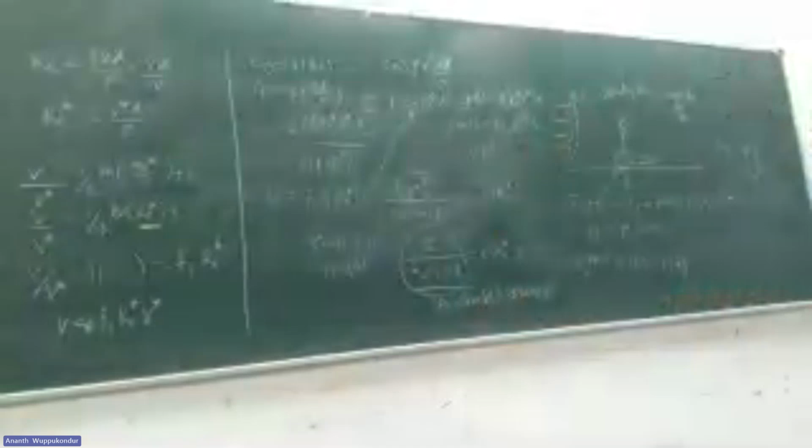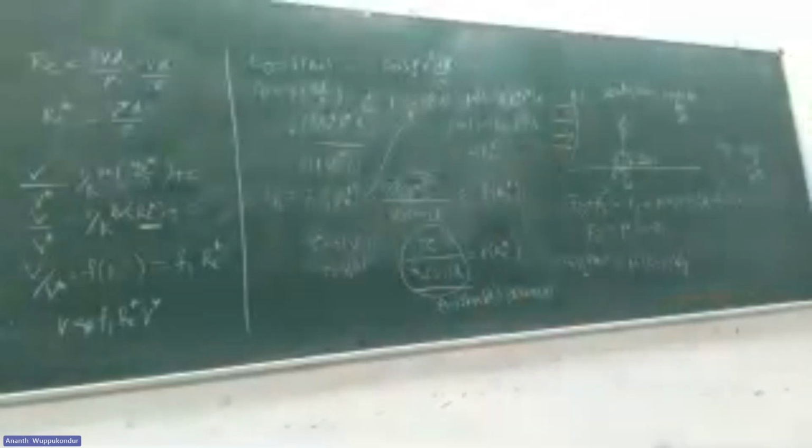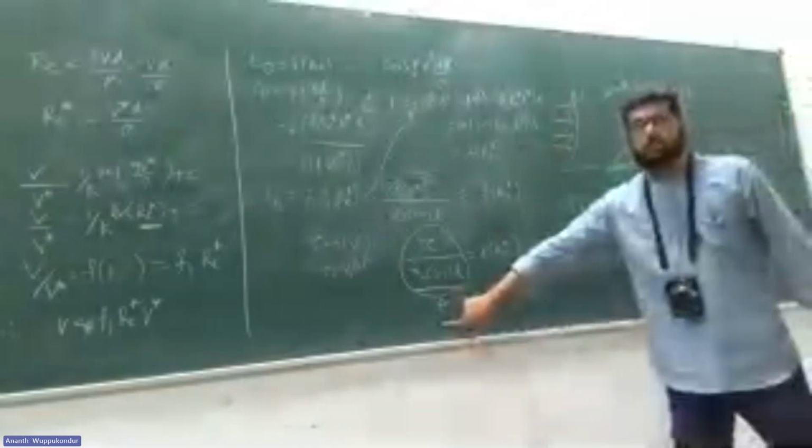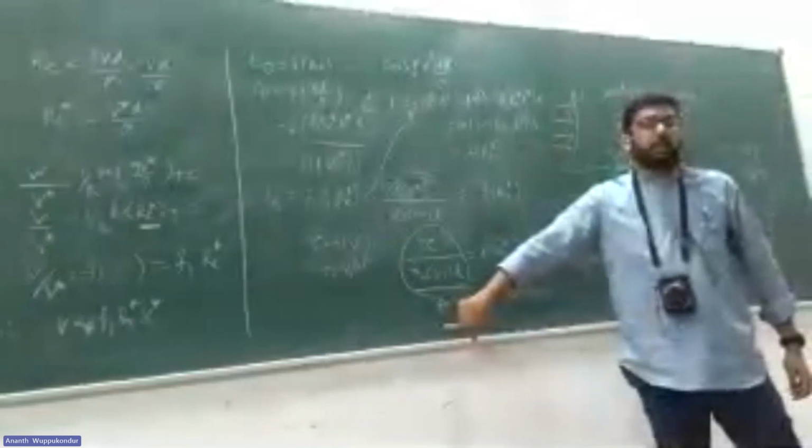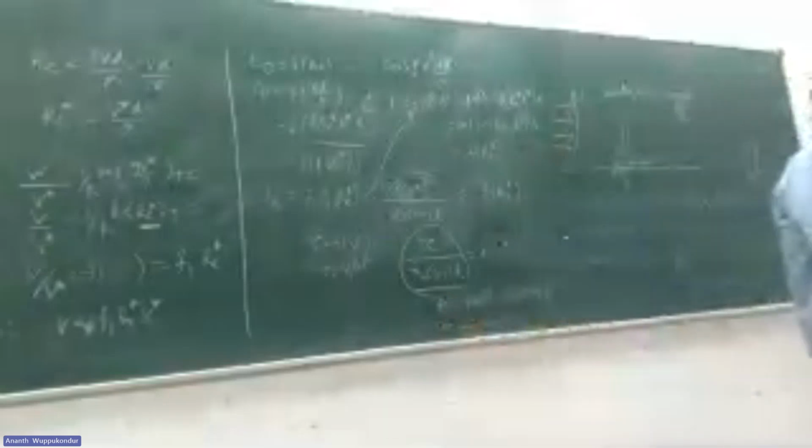So generally, when we design a canal, we know the flow conditions and what is the sediment size, and we estimate what is the Shield's parameter for the given flow conditions and the sediment size. And we will make sure that this Shield's parameter is within some limiting value, so that there is no erosion of the sediments.